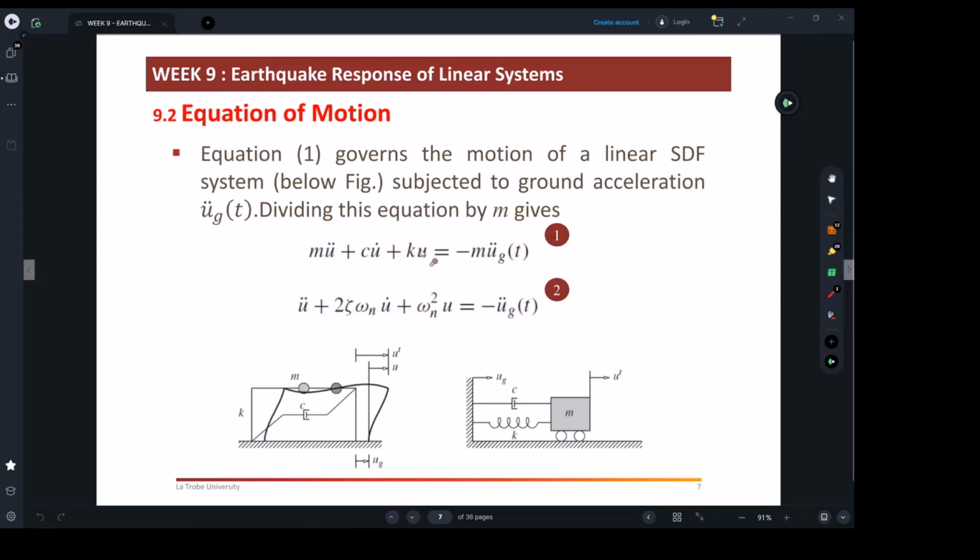We all know that the mass contributes to the overall stiffness. You also know that the mass contributes to damping. Inside the formulation for damping, there's mass. So we are able to divide the entire equation by mass just to take it away, and it will give you the same response. You can have a look here. There is no mass here. It's independent of mass.